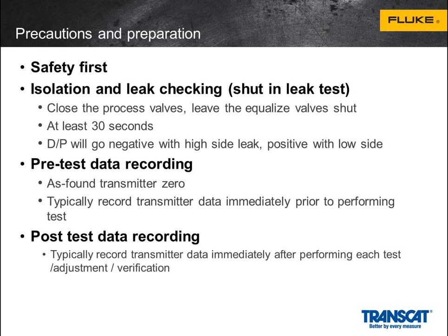If you have no or low flow, you may have other problems, especially for a differential pressure meter. They're really not designed to go much outside their 3-to-1 or so turndown ratio, and if your flow conditions drop outside of that, it's very easy to see zero drift. So this rule of thumb only applies when the unit is isolated and you're doing a leak check.